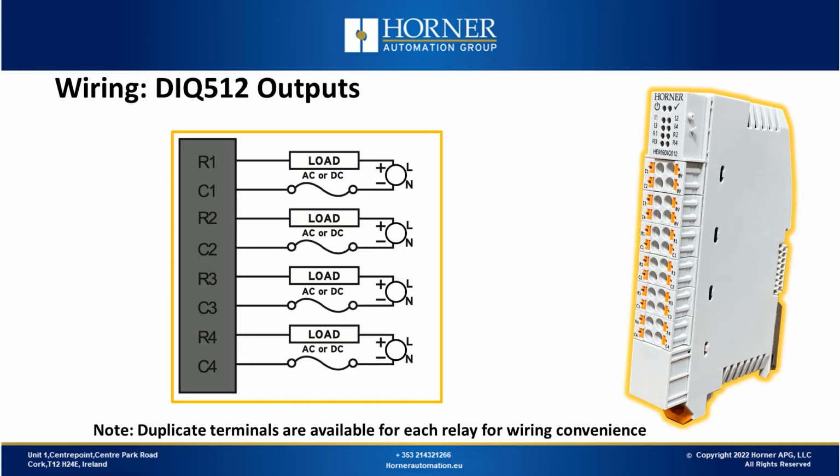In terms of wiring, we can see here we have isolated outputs, which means each relay is wired separately from each of the others. Also, we can see fuses in the wiring diagram. Anytime you're using larger relay loads, you should look at fusing, and the rating for the fuses are going to be dependent on the load sizes and the wiring gauge.